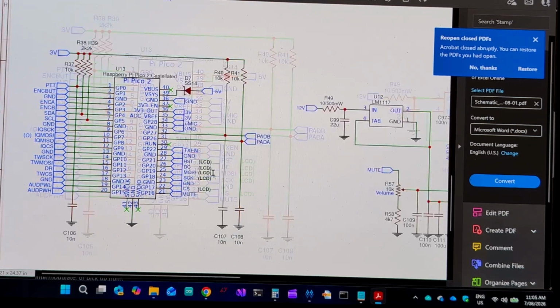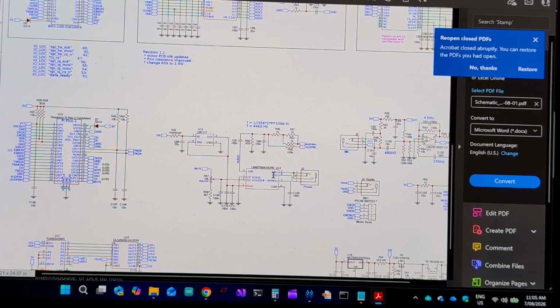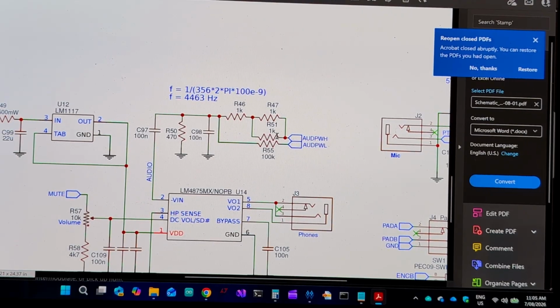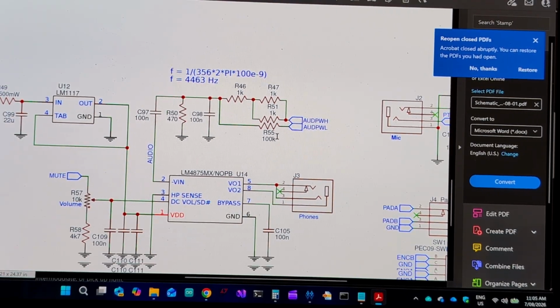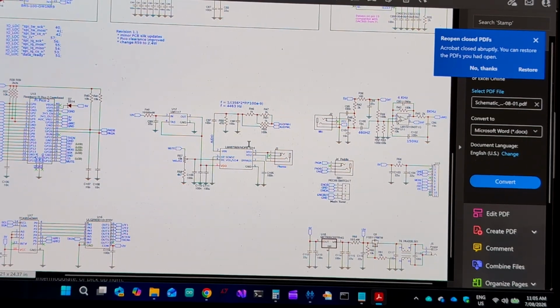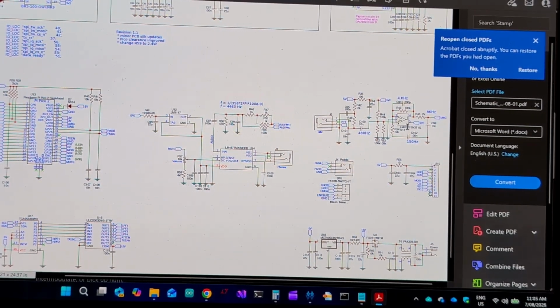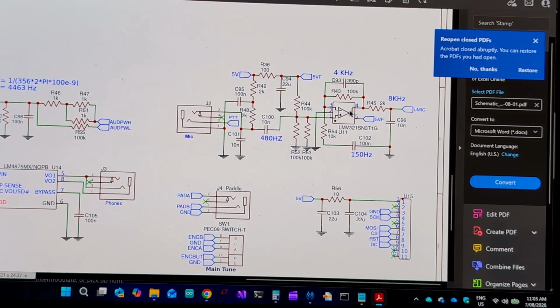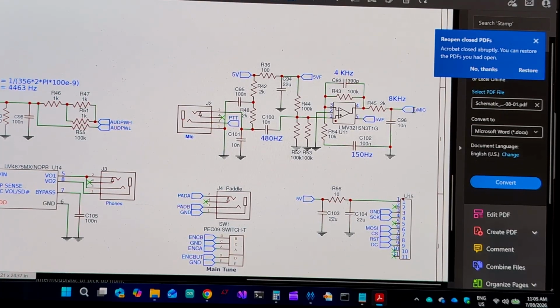And when we have the audio. So the audio is generated from dual pulse width modulated pins from the microcontroller. It's the same as the phasing transceiver, and the microphone input biasing for the electret microphone, a single op amp amplifier straight into the ADC of the microcontroller.